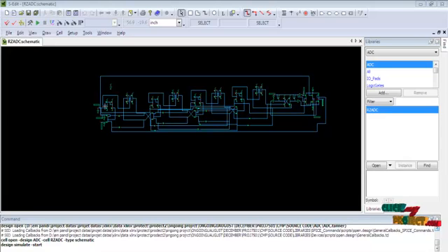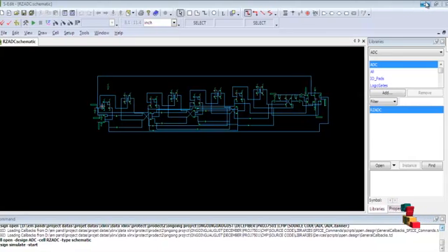This proposed implementation is done in the Tanner EDA tool, in the SEdit tool. First open the SEdit tool and create a new cell. After creating the new cell, we update the library file in the simulation parameter. After updating that, we draw the corresponding circuit as per the base paper. After arranging the circuit, we click the run icon, then the T-Space window will open.